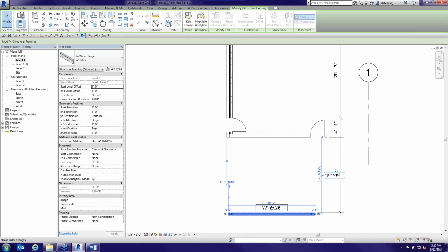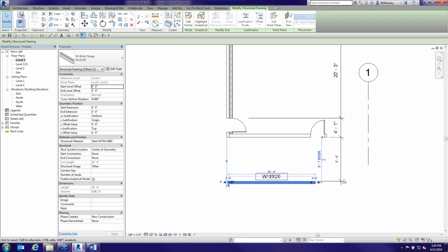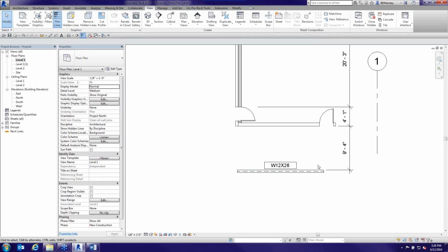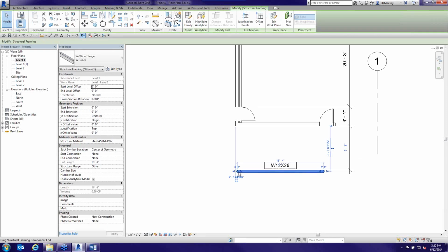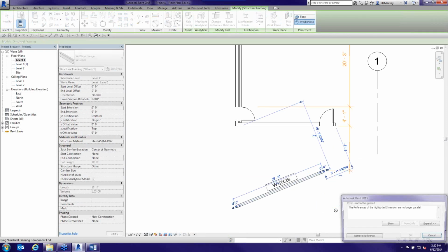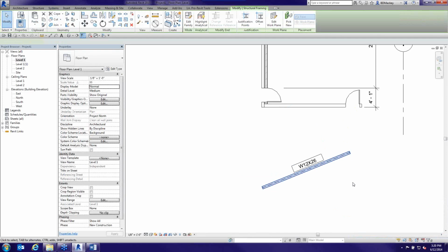So when you're doing formulas in here, you can type in 42 feet 8 inches divided by 3, and you'll start to see, hey, look at that, I've now figured out that's 9'4". So for me, a lot of times I'm going to be coming in here and setting this up, doing the formulas where I get into it.